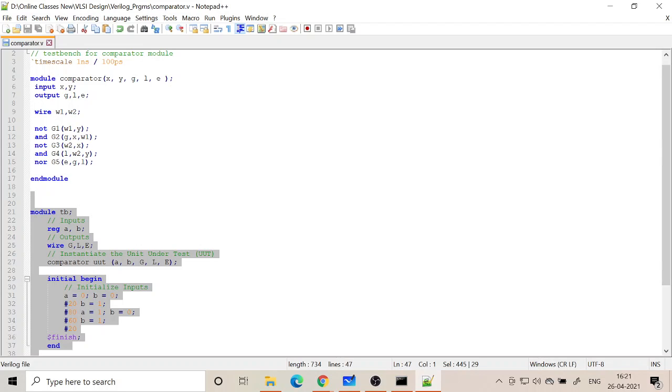Okay, because we are giving more details to the synthesis software, and synthesis software is very costly software. It is because it involves much more computation, not just compiling a program. It is generating the circuit from your program. So it has to read the program and understand what all hardware, what is the way to implement the hardware. So it depends upon the way the synthesis software runs, it will generate the circuit.